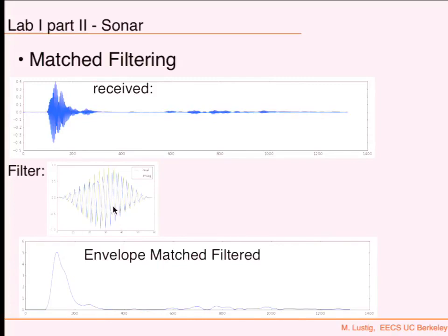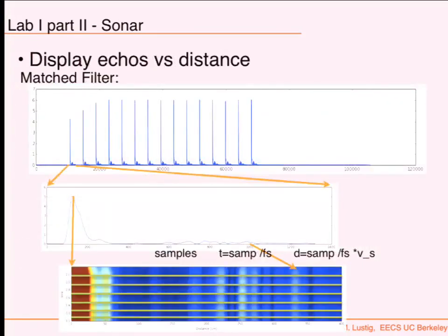That's why you're using the analytic function, because it's easy. Again, it's like a Hilbert transform that lets you look at the envelope. So that's what I receive. Any peak here is, in fact, an echo that comes back, which is kind of cool. Now I can send a bunch of pulses repeatedly, and when I do that, this is a pulse, and this is a pulse. They're all aligned.